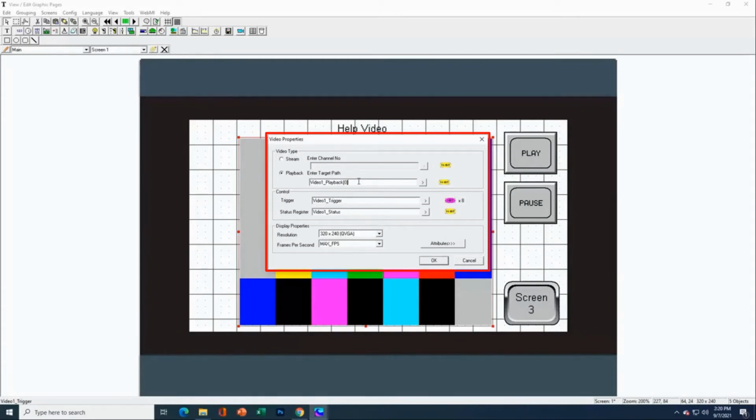You also need to specify an integer type variable. You'll need a series of them because it's interpreted as ASCII data with 2 characters per 16 bits of data. So I've allocated an array. I've got an integer type variable that is an array of 10 consecutive words, which allows me to specify a path file name of up to 20 characters.